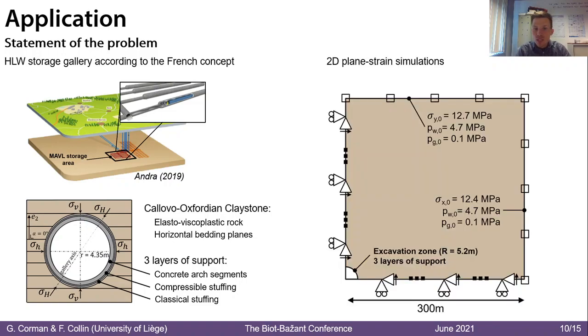This figure gives an overview of the mesh of the model in plane strain state, with all the initial and boundary conditions required for the simulations, and only a quarter of the domain is considered due to the symmetry condition.